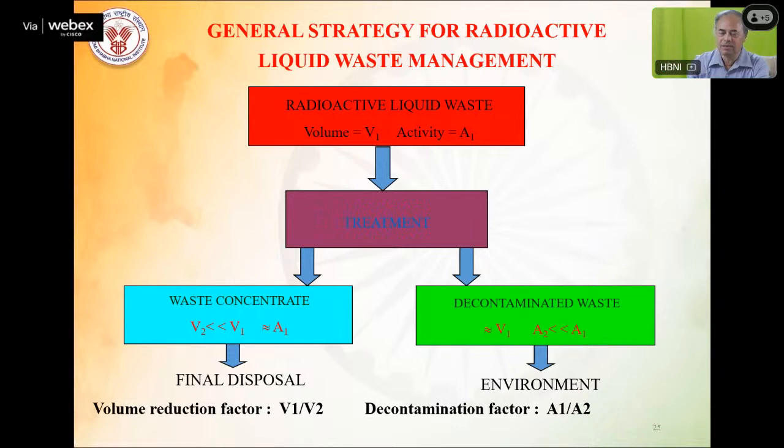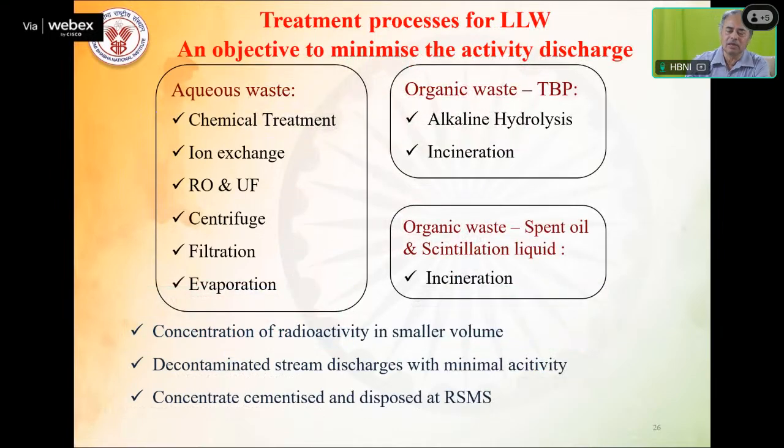That is the strategy adopted for low-level waste treatment. Now, the treatment processes of LLW, with an objective to minimize the activity discharge. So these are the processes, as I said: chemical treatment, ion exchange, RO, UF, centrifuge, filtration, and evaporation.